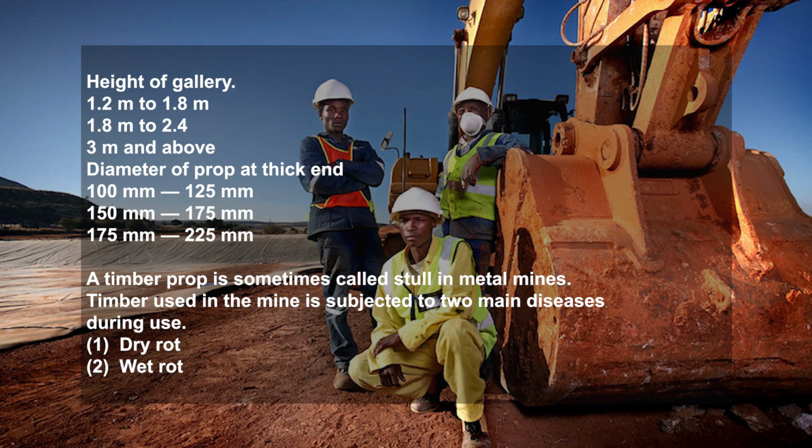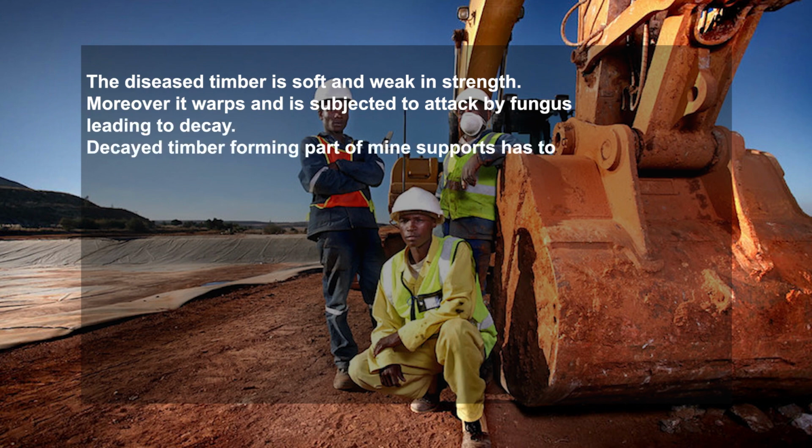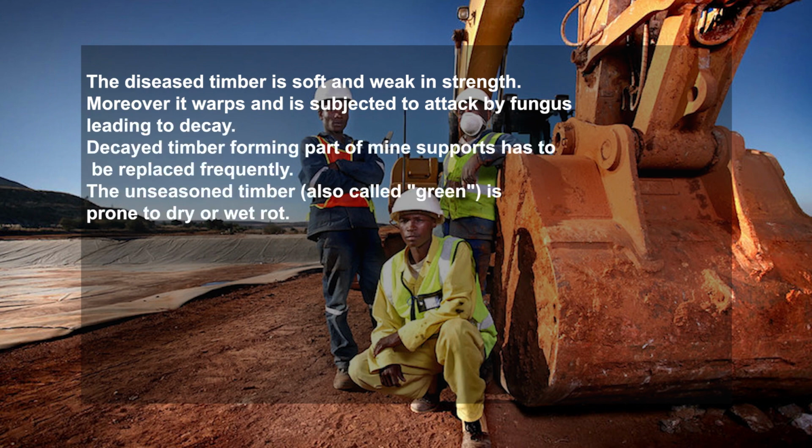Timber used in the mine is subjected to two main diseases during use: dry rot and wet rot. The diseased timber is soft and weak in strength, moreover is warped and is subjected to attack by fungus leading to decay. Decayed timber forming part of mine support has to be replaced frequently. The unseasoned timber, also called green, is prone to dry or wet rot.